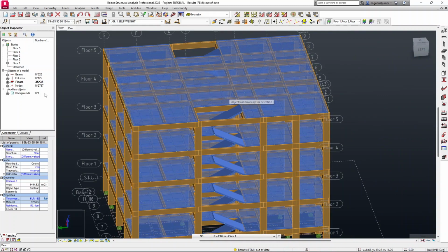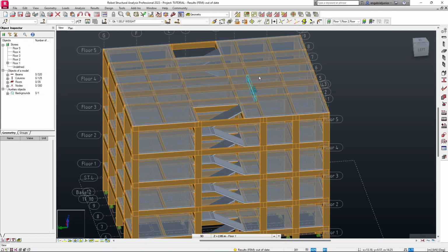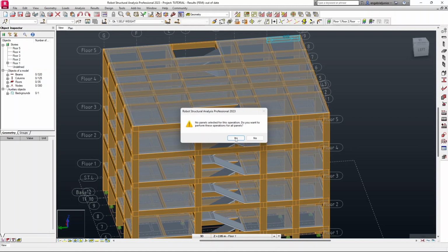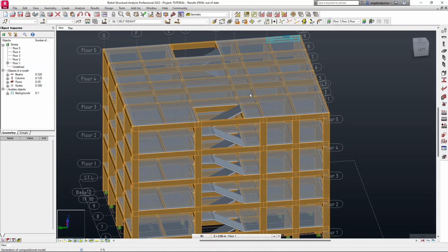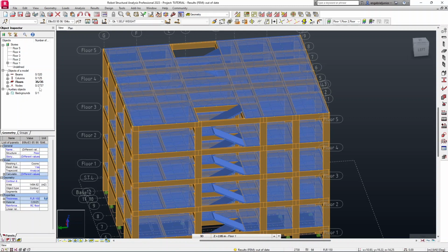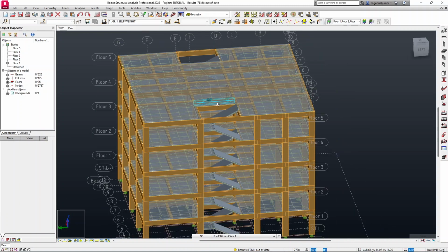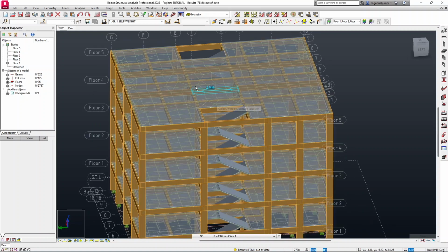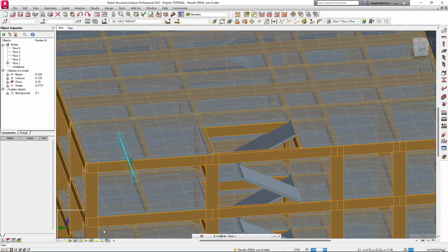Then one thing you notice is that the number of nodes has increased just to accommodate these new additions here. So if you were to delete the mesh, realize the nodes are 380 for the whole structure. But if you were to just generate, yes, they've gone up to 2,700 over there. So that's it on meshing options. If you wish to view or not view the meshes, you can just click on this icon here. So you can clear it or you can view it.